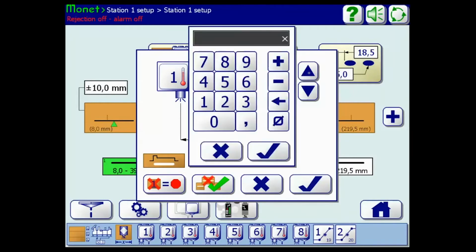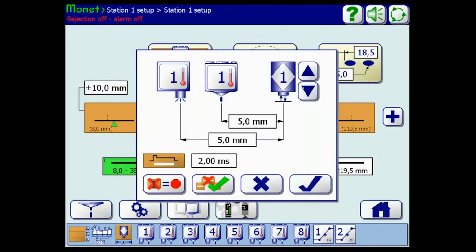Trigger assignment. Now, again, we should never really need to worry about changing the trigger assignment. We only have two triggers on the machine, and we know trigger 1 is assigned to valves 1, 2, 3, and 4, and trigger 2 is assigned to valves 5, 6, 7, and 8. But this is where we actually go to change the trigger assignment: this little up and down arrow right next to the trigger symbol. And Keith, that's another thing. Pretty much everything in this menu, once it's properly set, probably should be password protected with at least the manager level password. There's really no need to change any of these things once they're dialed in and set correctly.